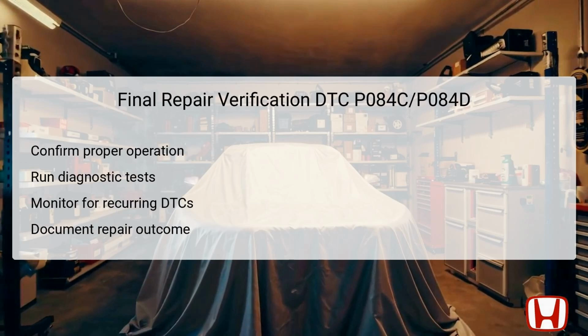After completing the diagnostic and repair procedure, it's crucial to confirm that everything is operating as intended. A thorough test drive of the vehicle should be conducted to verify normal transmission operations. It's essential to run diagnostic tests again using the Honda Diagnostic System, HDS, to ensure that all DTCs have been cleared and that no new codes appear.